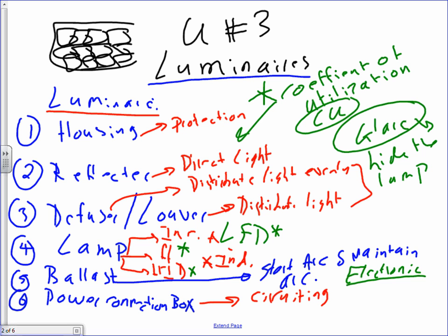Two reasons. You boost the voltage in order to start the arc. Now we're arcing. When you arc, there's high current. If you don't reduce that high current, guess what is going to happen to your circuit breaker? Trips. It's going to think it's a short circuit, right? So after you boost the voltage, we start the arc. The arc starts to maintain and sustain. The current starts going through the coil, develops resistance, and it chokes the current and brings it down to the level of the fixture. Cool?